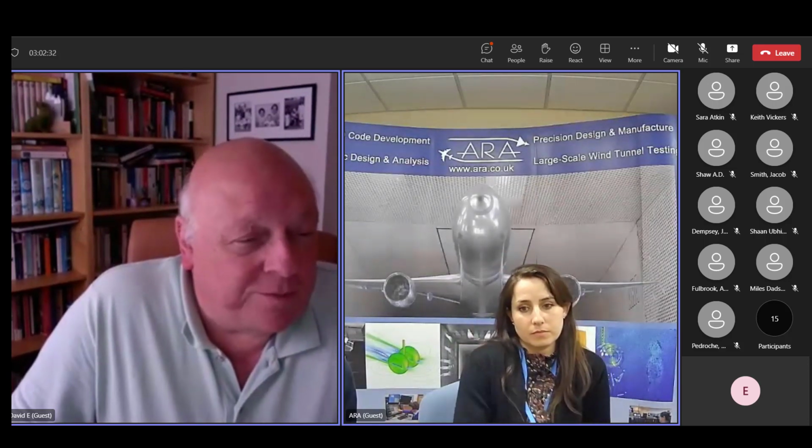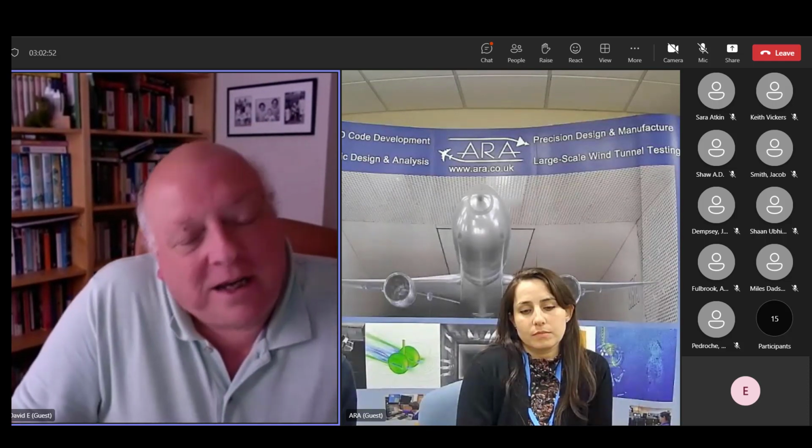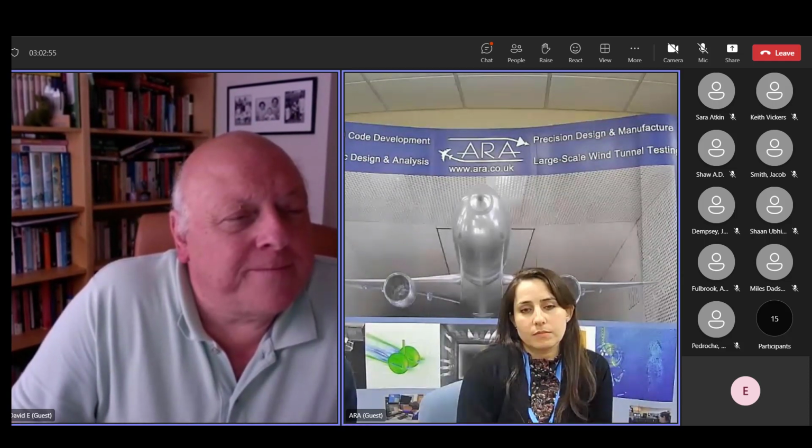So we're mostly interested in axial force for this because it was sort of a jet effect thrust coefficient measurement that we were interested in. That's good, because I was in a similar position to you when I used to work at MIRA, the Motor Industry Research Association, and we used to build very similar load cells to what you've built there for measuring engine loads and gearbox loads, probably similar ballpark in terms of loading themselves for 6 degrees of freedom. And one thing that I spent a lot of my time doing is actually looking at the crosstalk that is induced, as well as the thermal loads, which are very important, and it's a very interesting technique. How do you guys handle crosstalk measurements?